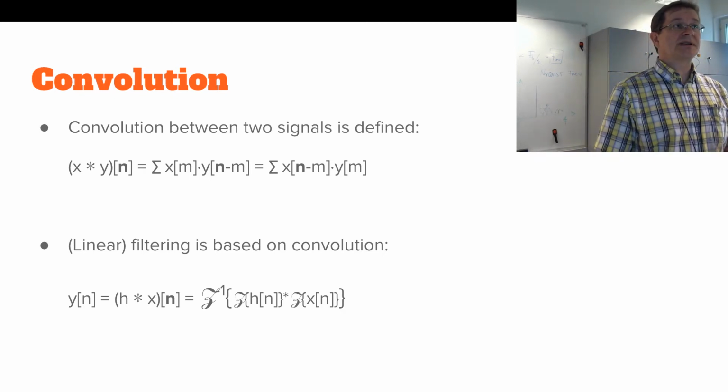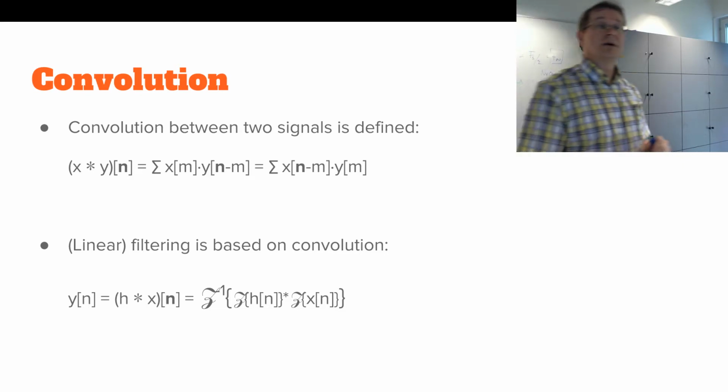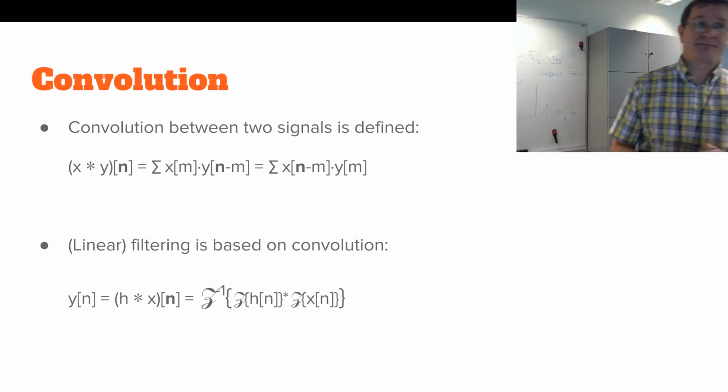The difference is that we do not correlate anymore, but we convolve, meaning we take the spectral properties of the snap, for example, and run it through the signal here. It will clean the signal so that wherever we have similarities it will show the same signal, but the noise level has gone down. That is called matched filtering.